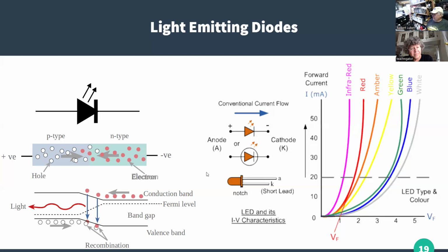These don't have a stripe because they don't have two wires coming out. And what we do is, when they make them, one of the leads is cut shorter than the other. That's the cathode. The longer lead is the anode. Also, you can't really tell here, but it has this little rim. It'll have a flat spot on the cathode side. Huh. Now you're gonna make me look at one.